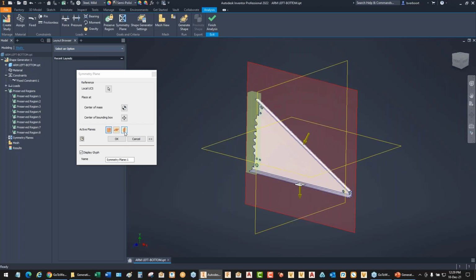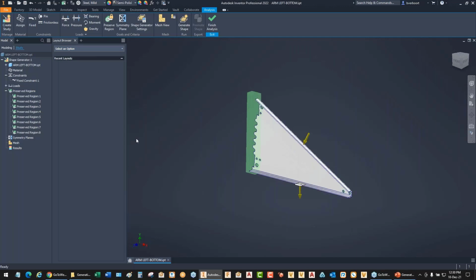However, you can apply symmetry, it's a great idea because it essentially cuts the calculation time in half, and your development time. So if this part was symmetrical, I could have probably just picked a couple of those holes and assigned symmetry, which means I wouldn't have to define all the holes. So it just cuts down my workload and also the processing workload that your hardware might find. Speaking of which, these calculations that we're going to be doing using generative design are done locally. They're not cloud-based.